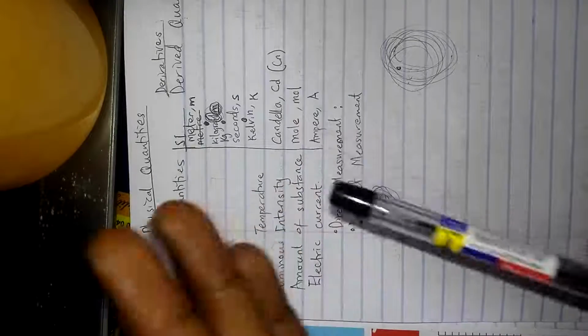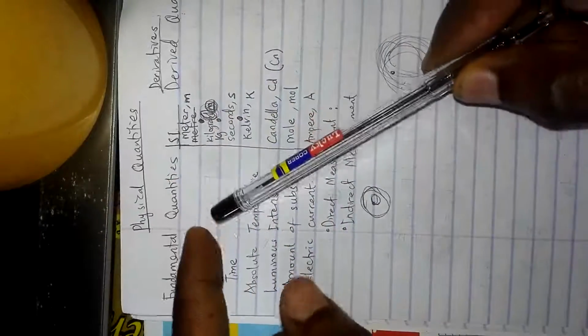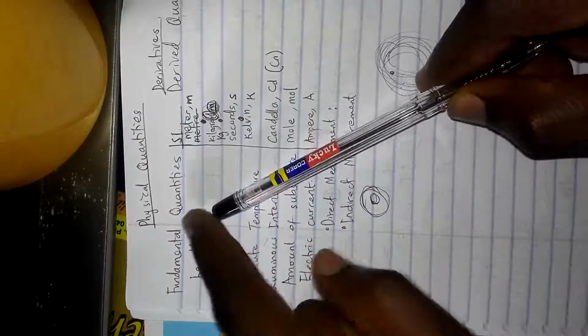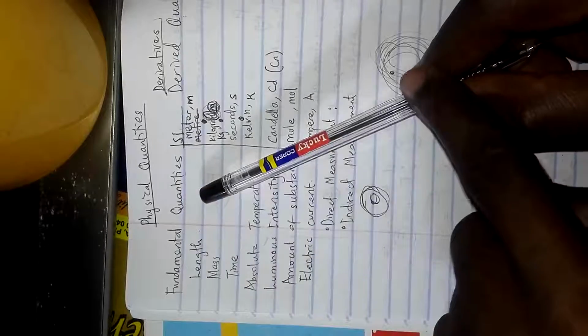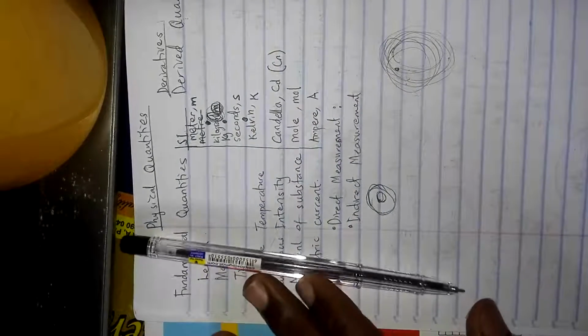Between those temperatures, this will have expanded and contracted. So if I continue to use this as the standard to calibrate another measuring instrument, I'm most likely going to make a mistake, because this may be longer or shorter than I originally intended. That is the reason why standards are used.